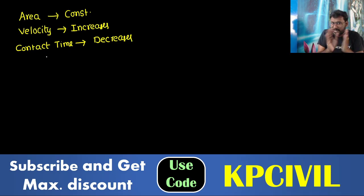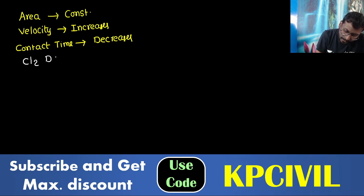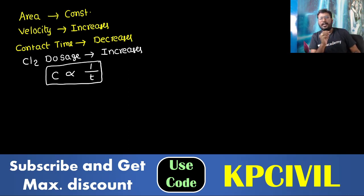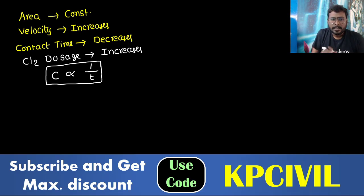But you want to maintain the same efficiency, you don't want to reduce it. Because of that, the chlorine dosage has to be increased. Contact period and chlorine dosage are inversely proportional to one another. C is inversely proportional to T. Chlorine dosage is inversely proportional to T. This is the relation between C and T.